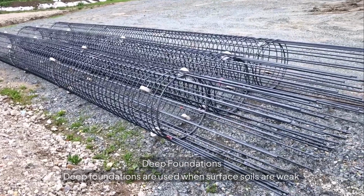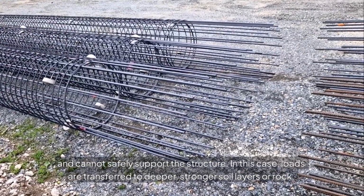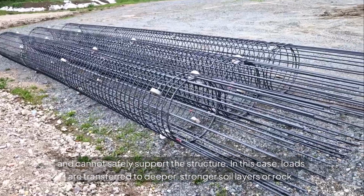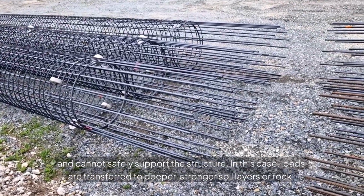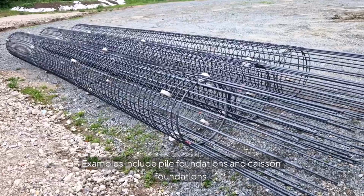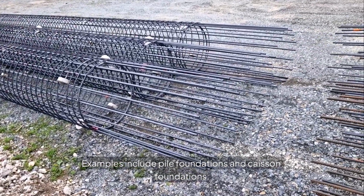Deep foundations. Deep foundations are used when surface soils are weak and cannot safely support the structure. In this case, loads are transferred to deeper, stronger soil layers or rock. Examples include pile foundations and caisson foundations.